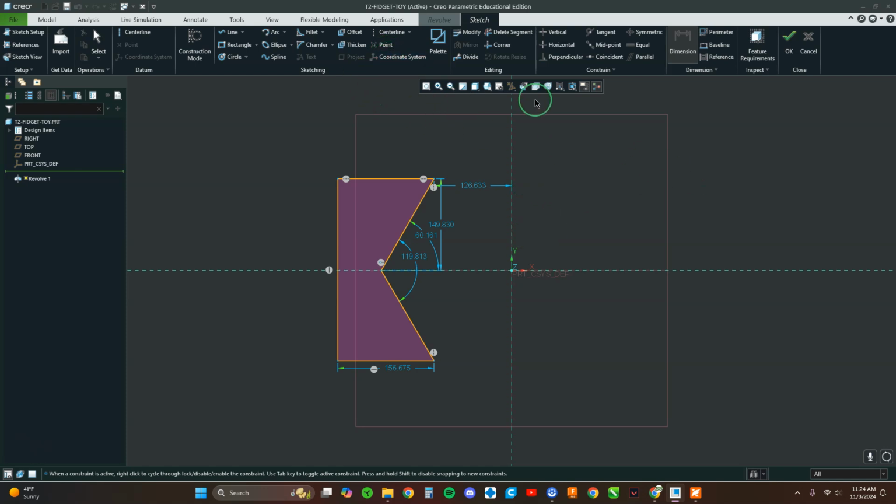And actually I forgot a very important part. It's a round thing, right? So we need a center. So before we put those dimensions in, let's go up and pick center line up here, and then click right in the middle, and you'll see you get an infinite center line. I want you to snap that center line right to the vertical line, the one that goes up and down. Click, okay, then middle click to end it again.